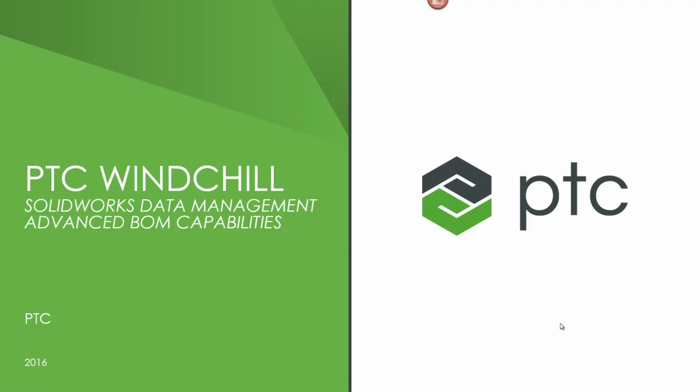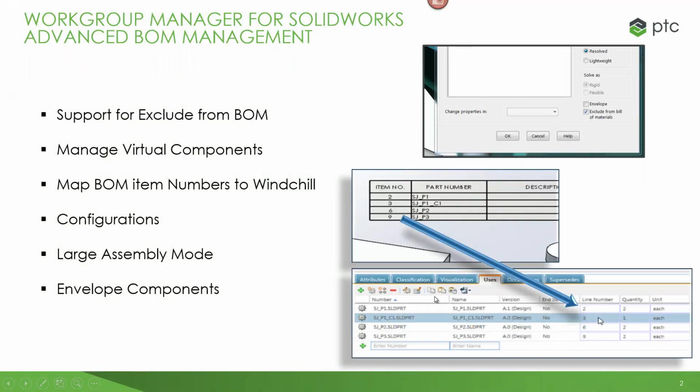Welcome. In this video we're going to have a look at some of the more advanced BOM capabilities that Windchill supports with managing SolidWorks data. Now Windchill has a number of capabilities for advanced BOM management. These include support for the exclude from BOM marking of components, management of virtual components, mapping BOM item numbers to Windchill line or find numbers, managing configurations for parts and assemblies, large assembly mode, this means loading in lightweight visualization, as well as managing envelope components.